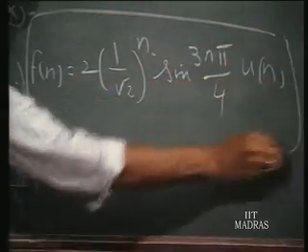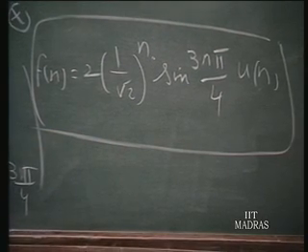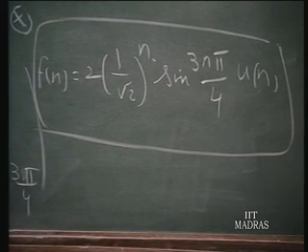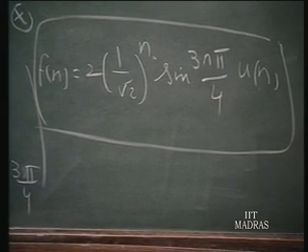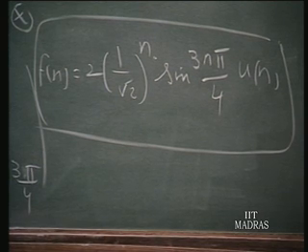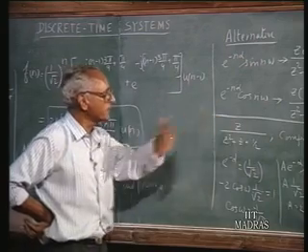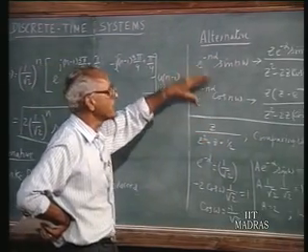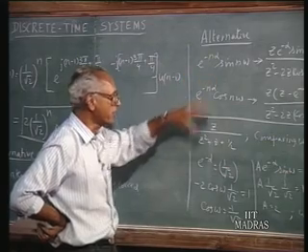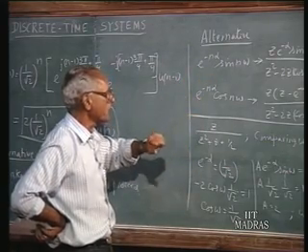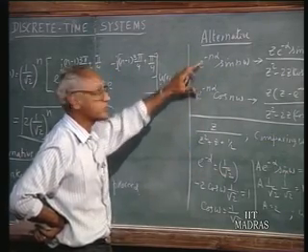So this is the result which we had already obtained earlier, but we have now obtained this in a more direct fashion. Whenever we have complex conjugate poles, it would be convenient to fit the given function with either one of these or both. Sometimes when you have a quadratic in the numerator, you may think of a combination of these two and try to fit the numerator so that it is an appropriate linear combination of the z transforms of these two functions.